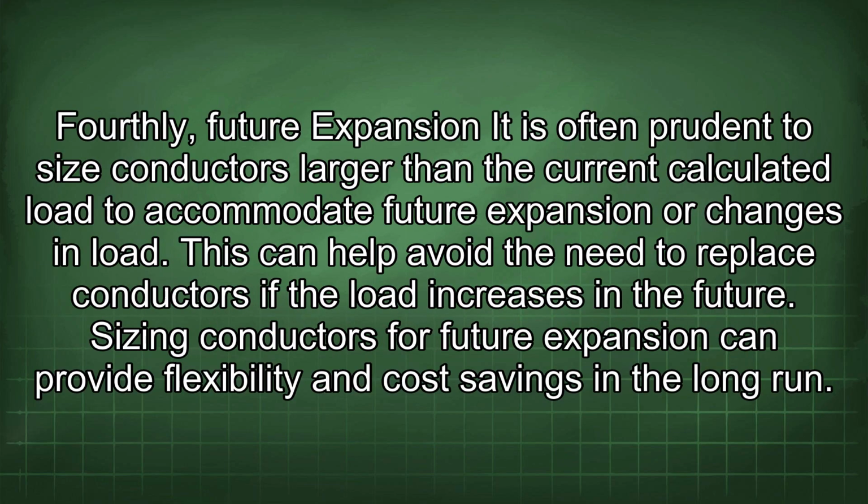Fourthly, future expansion. It is often prudent to size conductors larger than the current calculated load to accommodate future expansion or changes in load. This can help avoid the need to replace conductors if the load increases in the future. Sizing conductors for future expansion can provide flexibility and cost savings in the long run.